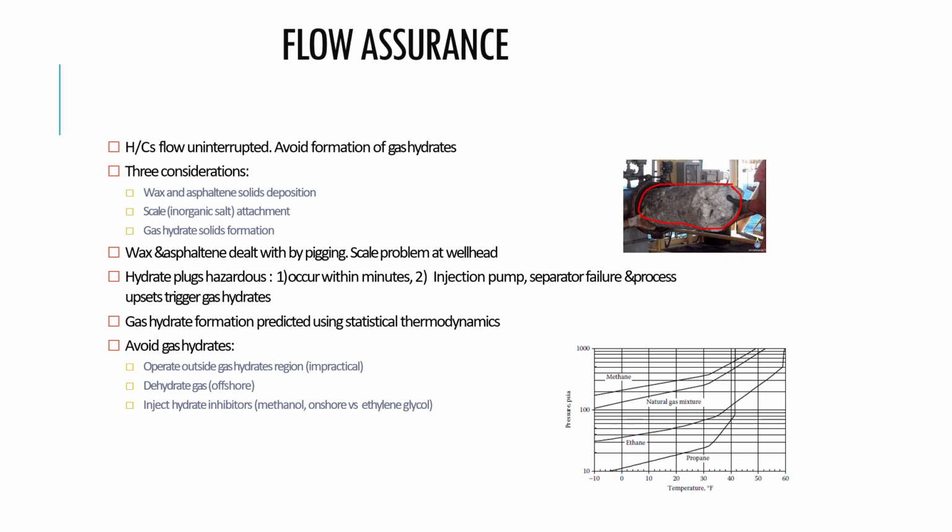For waxes, asphaltene and even the scales, this can be handled easily because pigging will take care of the problem: removal of waxes, removal of debris, and sometimes even removal of scales. This can be done using the pigging technique that we have seen before in the previous slide.